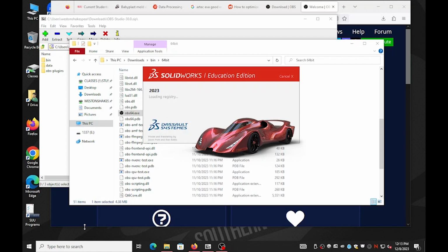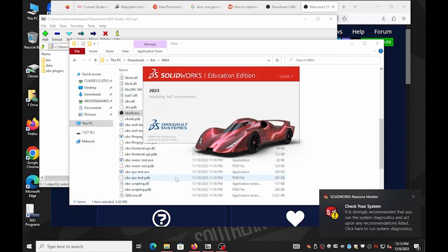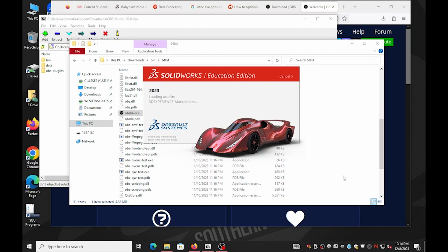As long as the mesh contains a small enough amount of polygons, we can directly import the mesh as a surface body in order to measure or reference any part of the model. Models that contain over 100,000 polygons will take a very long time to load in SolidWorks and usually won't be editable. Try to stick to around 20,000 polygons for a usable load on the system.